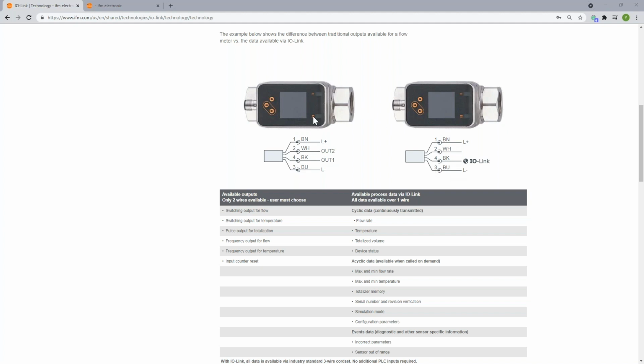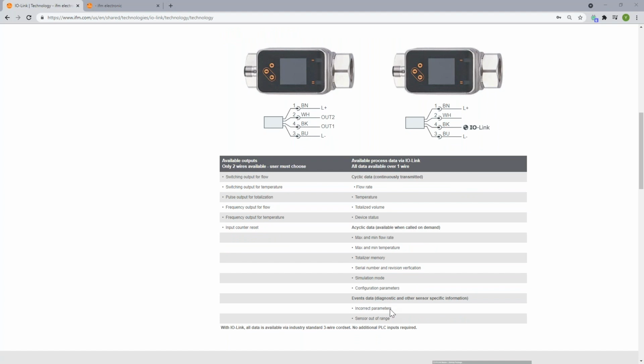Standard sensors today have microprocessors in there, but in the firmware you have to dumb it down to give you an on and off signal, which is what the one on the left-hand side represents. But if you connect this via IO-Link using the same cable, and in this case the same exact sensor, it allows you to unlock a lot of information that you can present to other systems, to your PLCs, to Ignition. This technology really allows us to bring smart data, really untrapped data that exists on your sensors, and make it available to other systems to use.